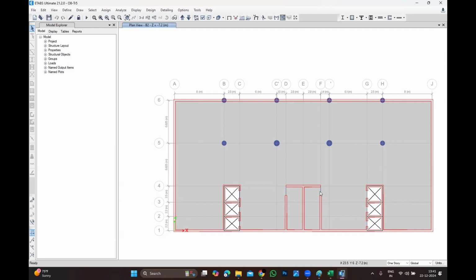Then in this case, you need to enter the entire data, not from the ground floor, because time period is related to it. Because the same thing is going to occur below the foundation. The displacement is only taken from the ground floor. How many basements are there? Even 4, 5 basements, it doesn't matter, because a basement doesn't move anything. If you take it, you underestimate. Right now, you're taking the full height, so you're putting in more margin. Basement will never have any impact.